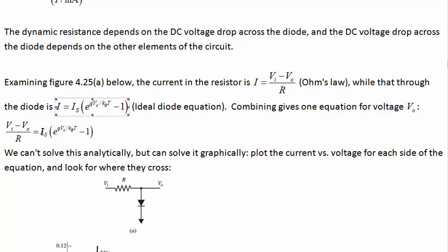If we combine these two, then, okay, now all we've got to do is solve for V naught. All right, go ahead. Take a minute to do that. Welcome back. How did it go? Right. Probably not the easiest equation to solve after you give it a shot. The problem is the exponential. You can't really get the V naught out of there without messing up what's going on the other side. So if you try and get rid of it, you end up getting a ln of V naught over here at least. So you can't really solve this analytically, but you can do it graphically.